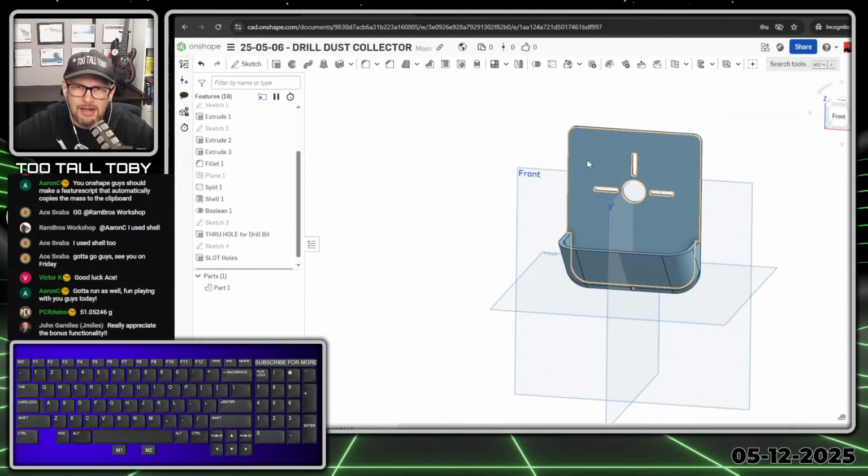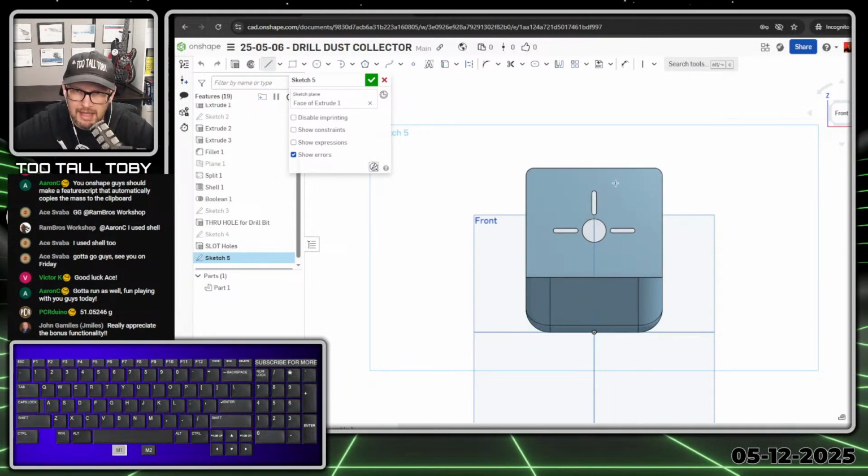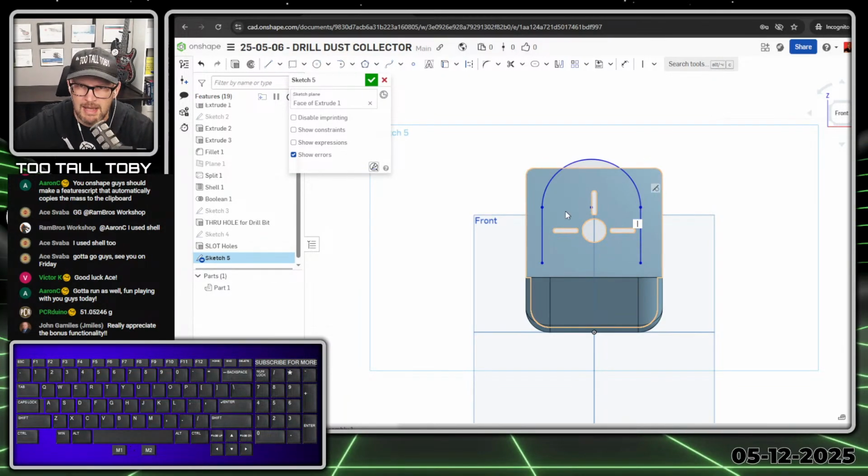And then finally, final feature here, pick this face, begin a sketch, N key, get normal to, S key, begin a line. You know, a lot of times we talk about using layout geometry and putting all of our geometry in one sketch. And certainly that's an option, but this is an option as well. You can see here that we can just create this geometry one feature at a time, and sometimes that helps to kind of keep your tree organized.